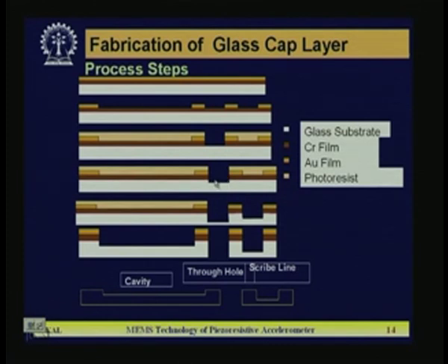You can see what has been done in the next phase. So here the window is open. After this region, on the left side there is another window, where the gold was removed earlier, so that portion is open now. So here also you start etching. During this step, here also it will continue to etch. So here the etch depth will be more compared to the side depth.